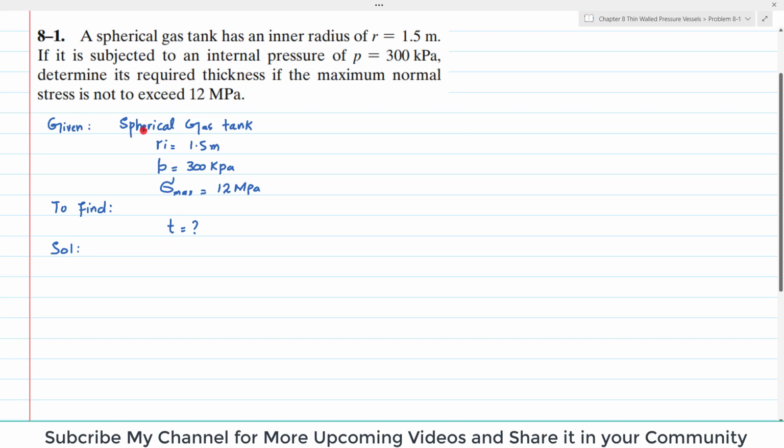As we know that spherical gas tank is given, so its allowable stress is given by the formula P into R divided by 2T, and this R is inner radius. Clear? So P into Ri divided by 2T.